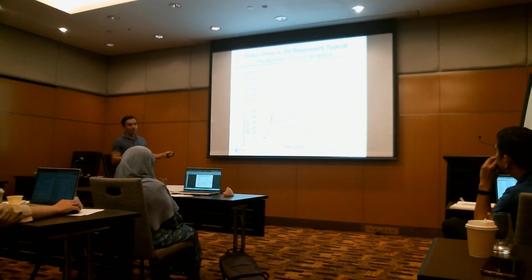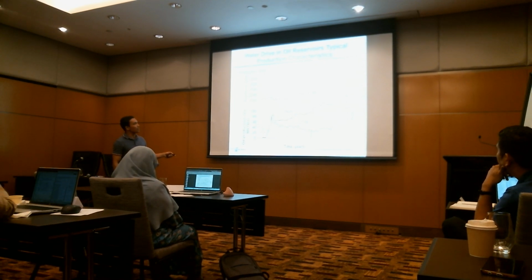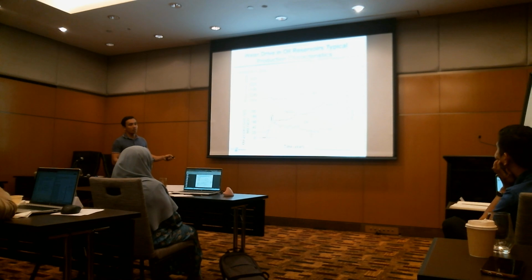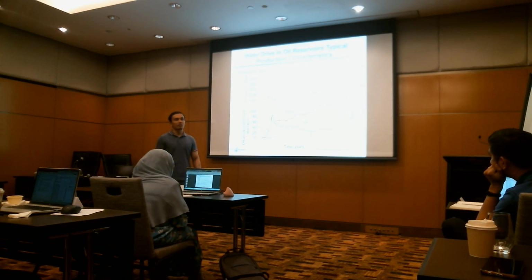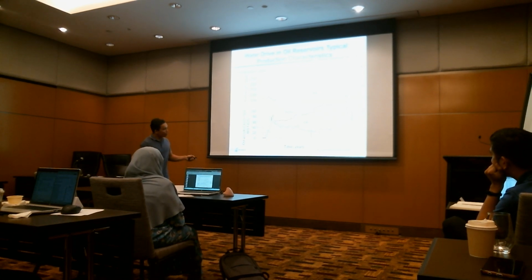And the water, I would say, is the glaring characteristic. You can see the water keeps increasing. Sometimes in the graph towards the late life of wells, you can see the water cut probably more than 95%. It's a lot, and you can have a long tail actually. At that time you have to decide when you want to abandon, depending on your economics.